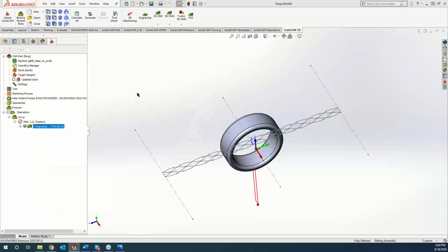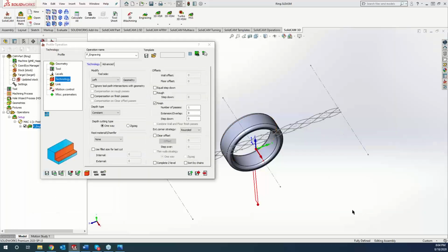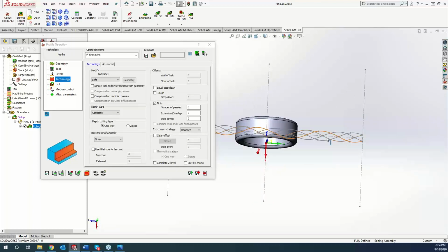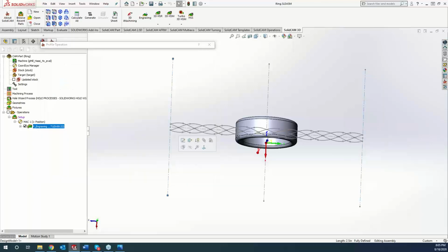Basically all we had to do is take that sketch and create it in a standard flat plane, so we didn't have to wrap it right to the face at all. The distance between this line and this line is the entire diameter of our circle there, so I just kept it contained within those boundaries. That way, when it goes to wrap it on there, all the geometry will line up just perfect.